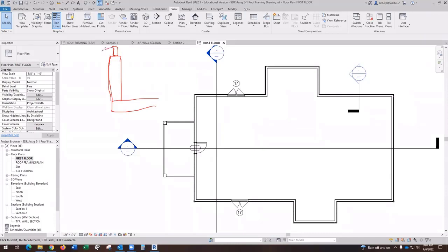And then the roof sits on top of that beam. Now you don't need the energy heel on that one, so you can do whatever you want as far as the thickness of that roof and how high it sits up above the beam. Now, depending on your overhang and your roof pitch, you might not actually see that beam, but having the beam in there makes it nice so that you can snap the roof to it. So I couldn't find a pre-made one, again, I was trying to work fast.